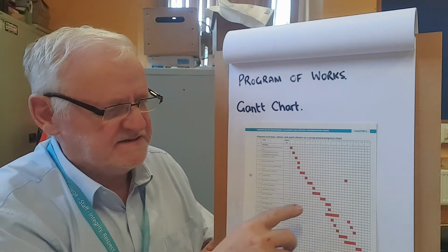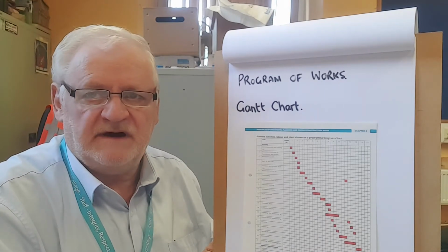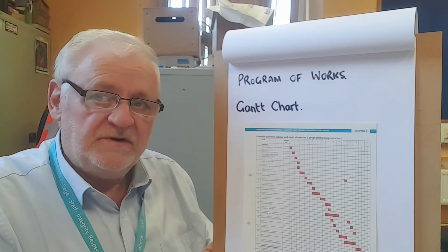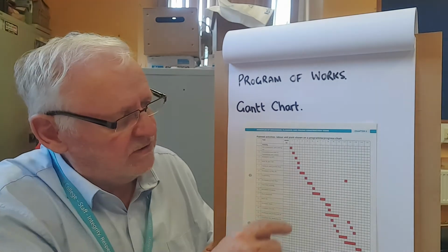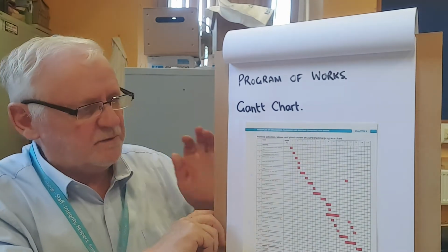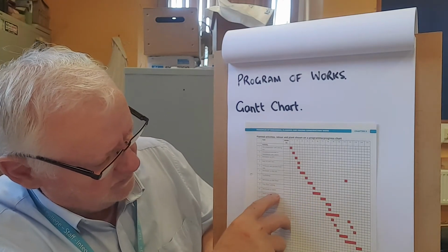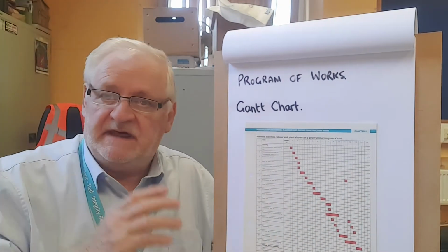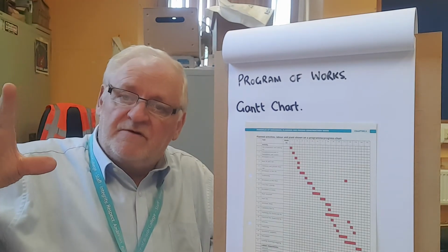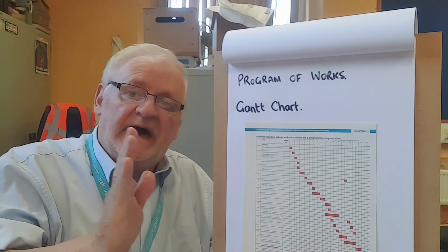What you do notice is that sometimes jobs are out of order. They're not always in exactly the right order. It's not always a perfect line coming down. But what you can do with a Gantt chart is look at the date and at your watch and say, all right, we're in the 6th week. So in the 6th week, we should be working on this particular thing, brickwork up to eaves. So you can then look at the building and say, oh, right, we're way beyond that. We've actually got the roof starting to be constructed. So that means that on the overall project, we're ahead.